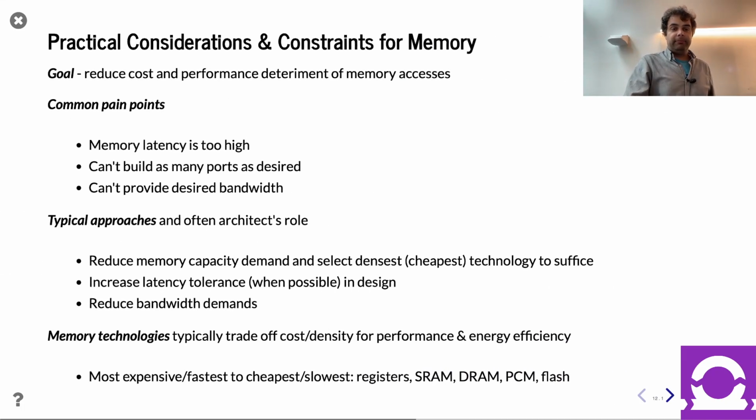Cool. Okay, so as we spoke a second ago, what are the constraints on memory? Very often, latency is the thing that drives us architects' bets. For off-chip DRAM latency, oh my gosh, we're tired of waiting for it. It's too high. Guess what? On-chip SRAM latency is also a problem, right? Unless you have the absolute best foundry-provided memory compiler SRAMs, it's usually going to be worse than your clock cycle. In other words, a one-cycle SRAM access will not always be easy to do unless you really, really have a fancy SRAM. So yeah, latency is always a problem, right?